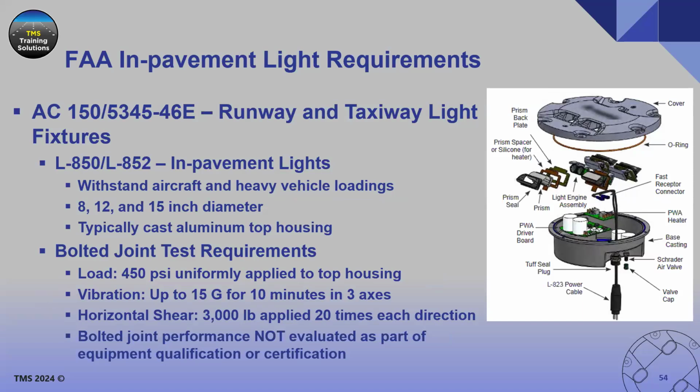You see the top cover, which is the part that's exposed, and that's the part that gets bolted onto the base can. The rest of the components just attach to that cover underneath and sit inside the base can with the isolation transformer and any other equipment that's needed in there. So 46E defines these requirements for runway and taxiway in-pavement light fixtures, specifically the L850 and L852 types.